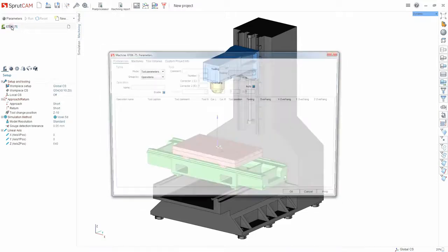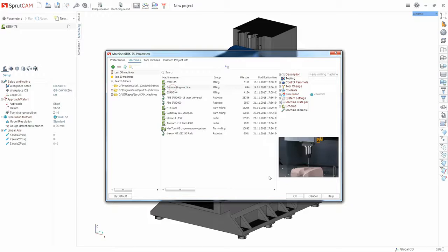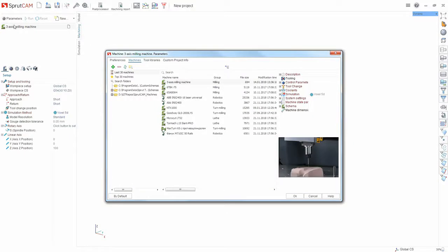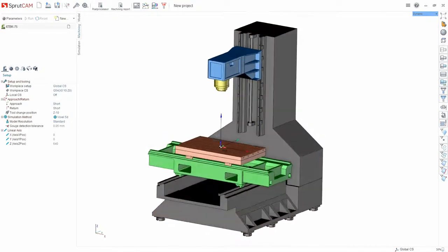If we switch equipment, select the Machine tab, select the Generate 3-axis milling machine, then in the process we'll only see our part and tool. We'll not see the machine scheme, but in this example we'll choose the real CNC machine. Double-click on the machine, and on the second tab we select some 3-axis machine, just so that we can see and understand where we have the part regarding to the CNC machine table.